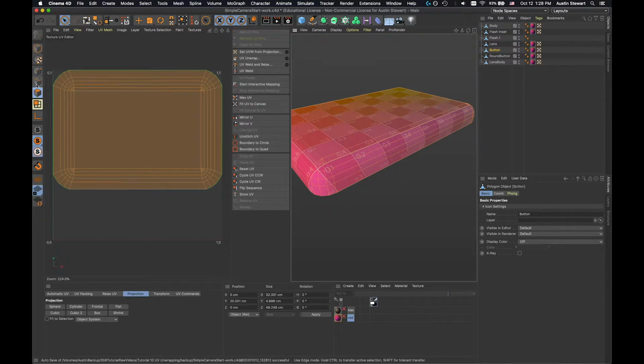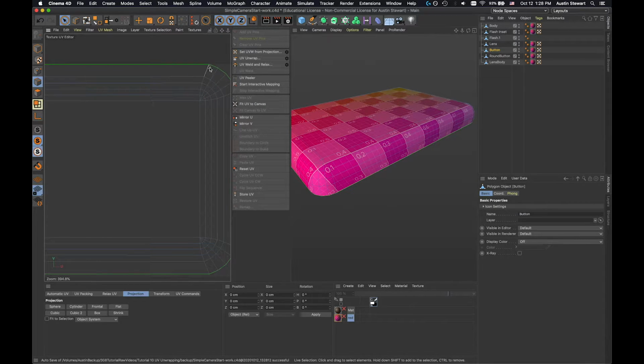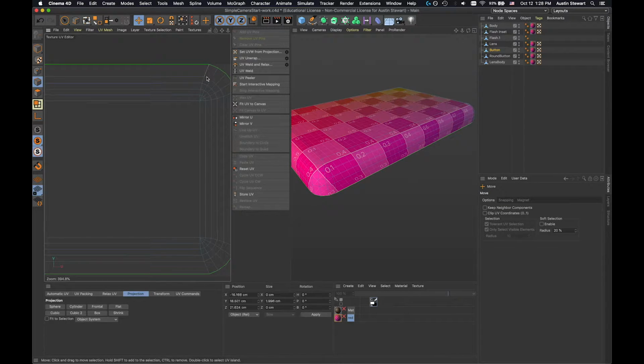And so I'm going to go ahead and switch to edges mode. And I can either use the live selection tool or what is sometimes simpler to do is to actually just use the move tool, because then I just hover over the line and click and I don't have that area of impact. And I just want to go ahead and choose some lines to cut.